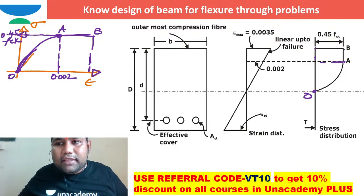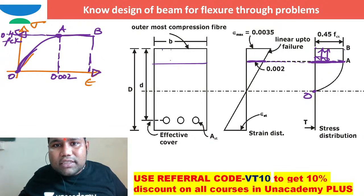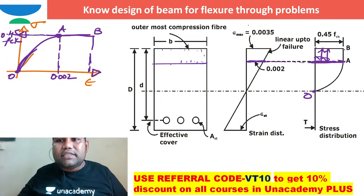So at point A, the strain is 0.002. From the layers above, from here to here, the concrete will start to crack when the strain in concrete has reached 0.0035, right?